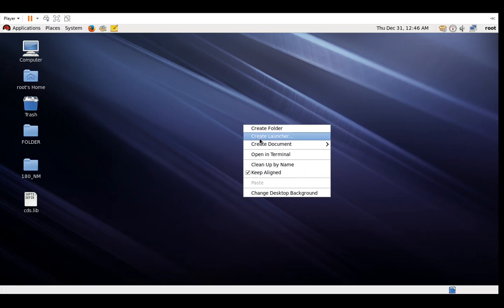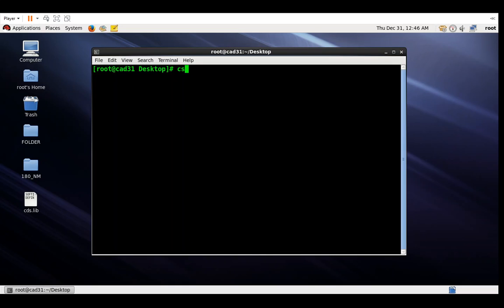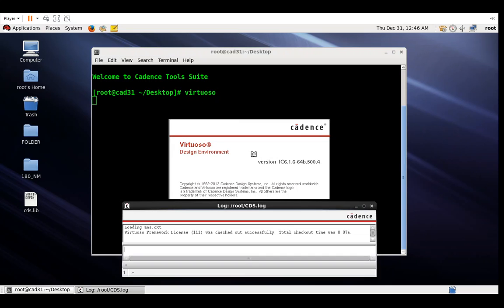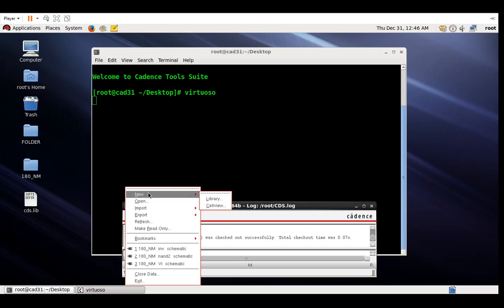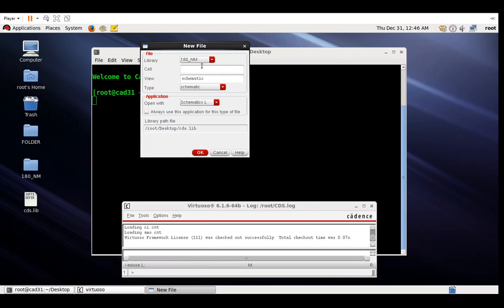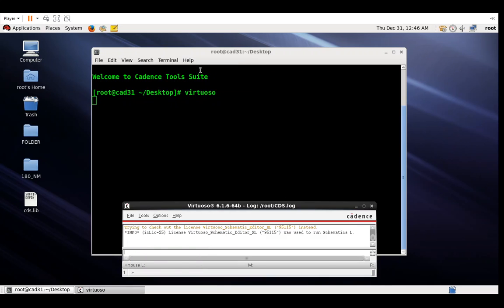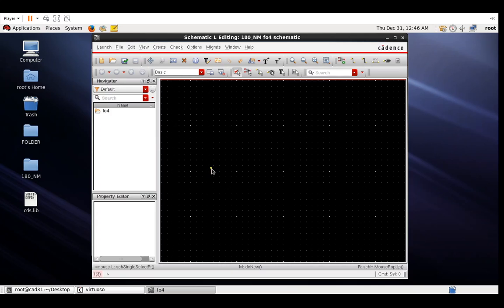So we will next do the FO4 delay. For that I will show the circuit and the procedure. Okay, so we will first do it for GPDK180. So file, new cell view, and we'll call it FO4 and insert the circuit.